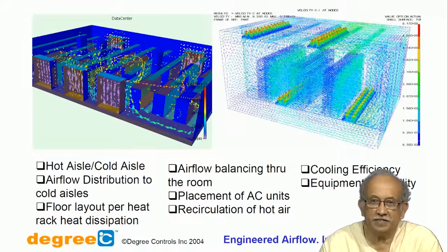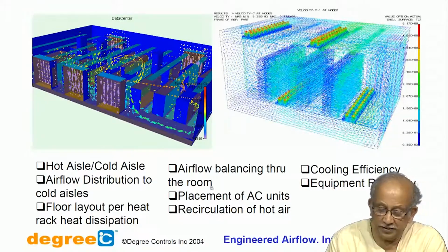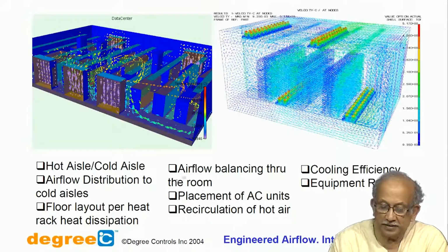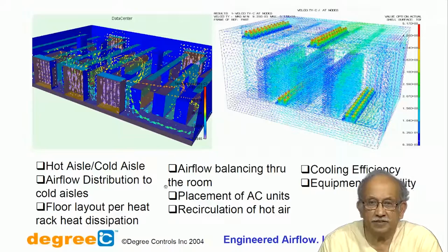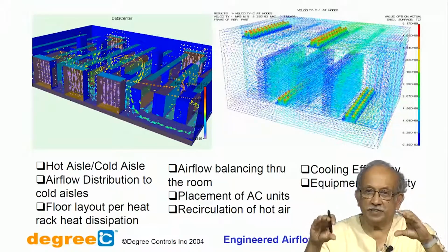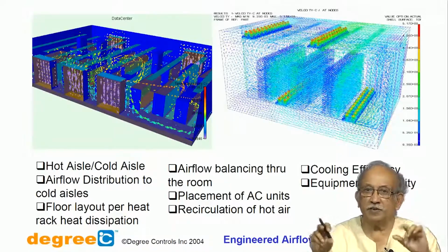First thing they do is play with the thermostat and raise the temperature. The moment you have it, the whole thing goes. So, the critical thing here is how do you balance the airflow. Whatever small louvers they give in the indoor units may or may not be sufficient.